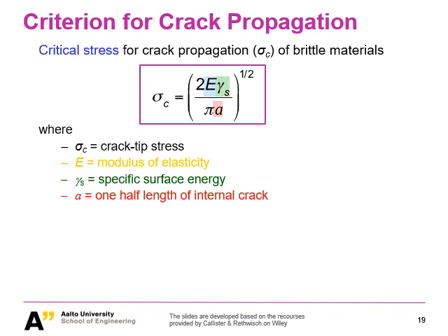Okay, that is good. And now we want to know how much this local stress would need to reach to finally trigger the crack propagation, right? I mean, we always get crack initiation because we have the defects, we have all these impurities in our material that will always develop various types of crack initiation triggers. But the stress always needs to reach a certain level to get the final crack propagation.